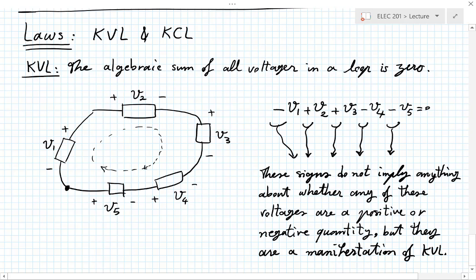So the question is to do the same thing as I did, except reverse your sign convention. If you encounter the negative side of an element first, include it in the KVL equation with a plus, and vice versa.